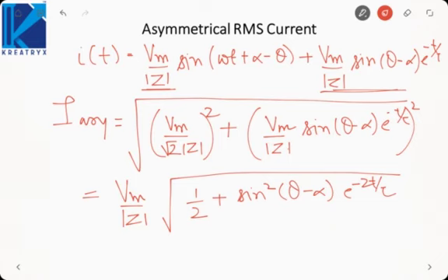Okay. Now if we observe that the current decays when we go from the subtransient towards the steady state region, the current is maximum in the subtransient region and minimum in the steady state. So where should we open the circuit breaker, in the subtransient, transient or the steady state?